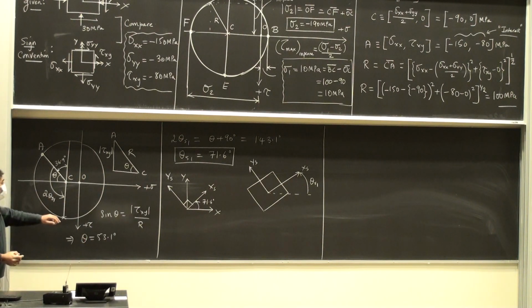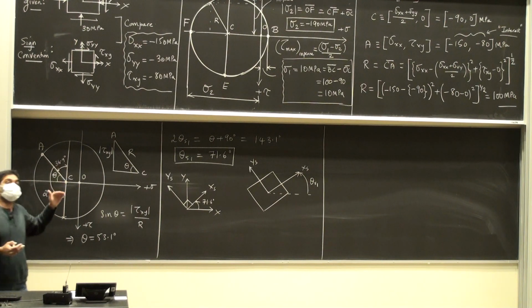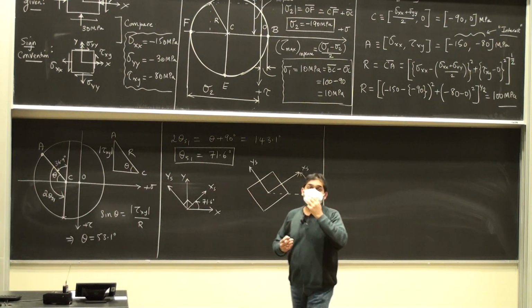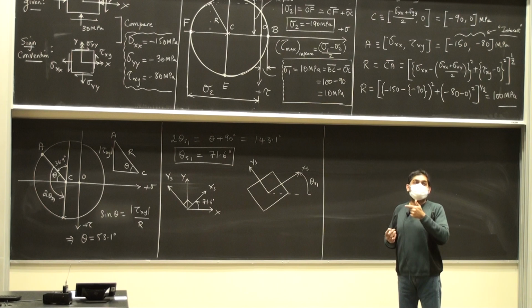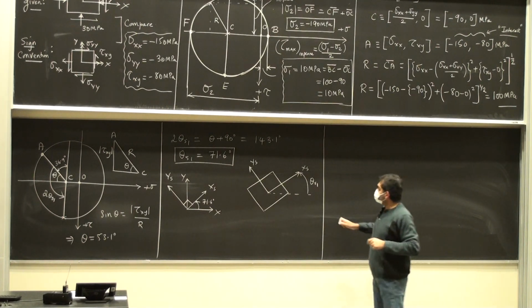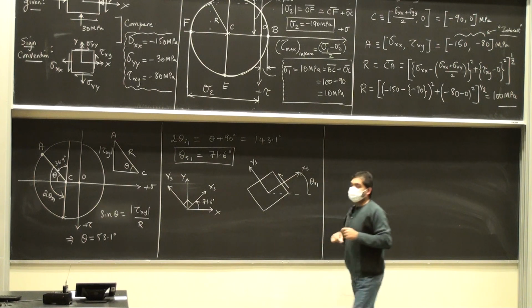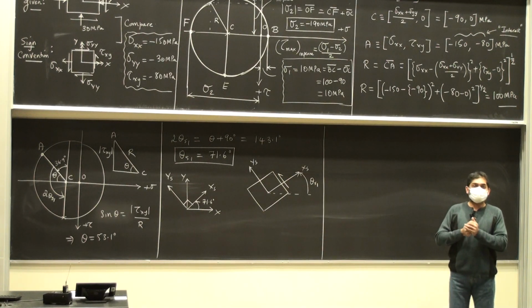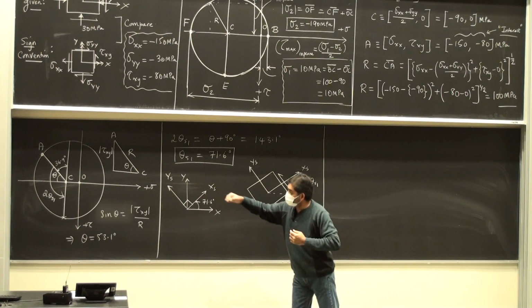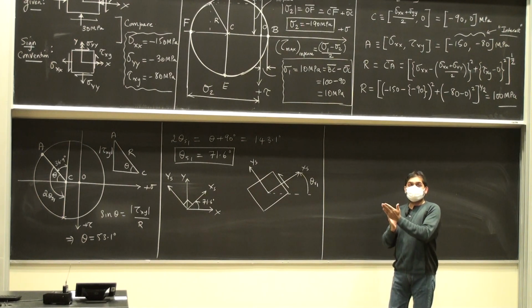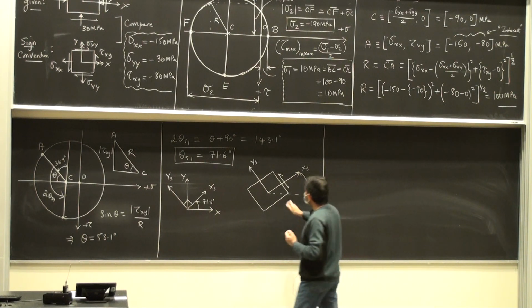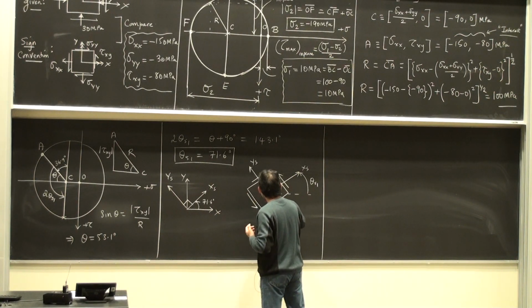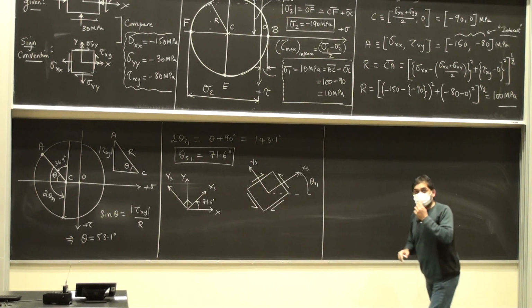So this is plus tau, plus sigma, which means that on the face that I'm interested in, which is always where the x-axis is pointing out, the direction of the shear stress has to follow the sign convention. Since I'm going to the maximum in-plane shear stress and that is positive, as I'm going counterclockwise, this is going to be directed in this particular manner. Does this make sense to everybody? I'm following the sign convention. I'm going to the positive maximum in-plane shear stress value, which means that the arrow has to be coincident with what the sign convention for shear stress is. If I find one of these, I find the rest of them. This way, this way, this way. So this is my tau max value.